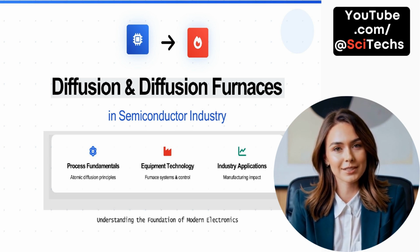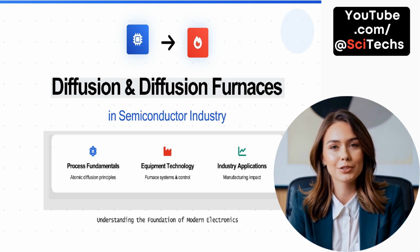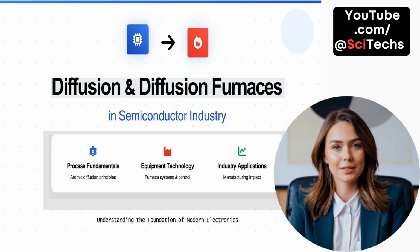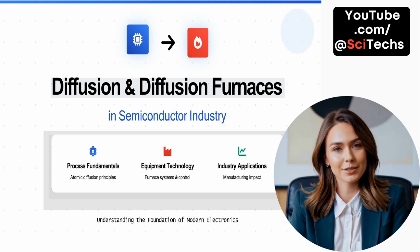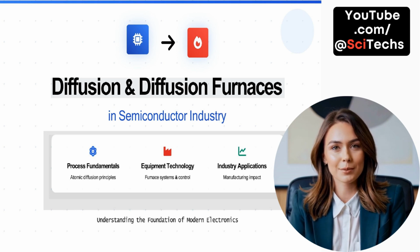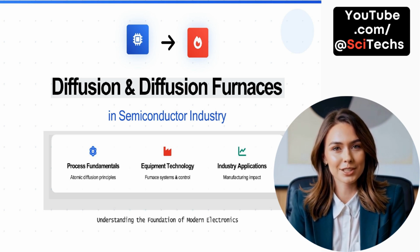Diffusion is a core process in semiconductor fabrication, where dopant atoms are introduced into silicon wafers to alter electrical properties and form critical device structures like source, drain, and base regions. This process depends on atomic diffusion principles, which govern how atoms move through a solid material, influenced by factors such as temperature, concentration gradients, and time. Understanding these fundamentals is essential for process optimization.